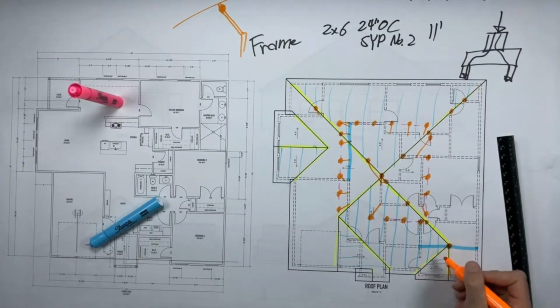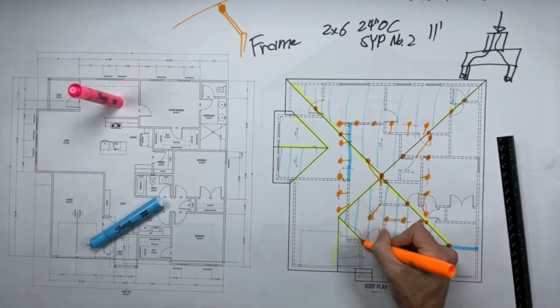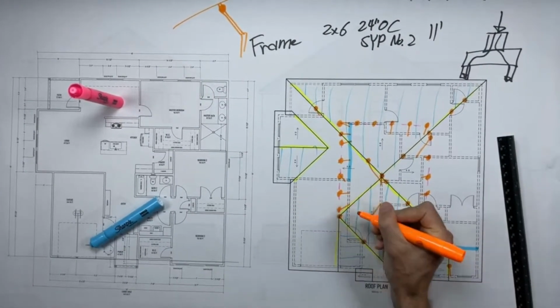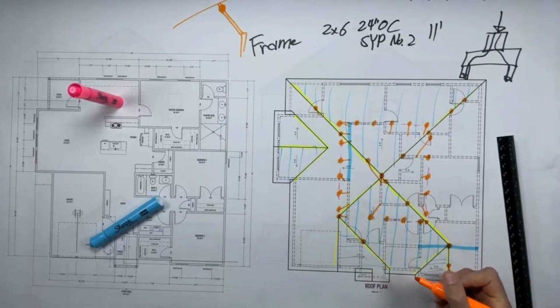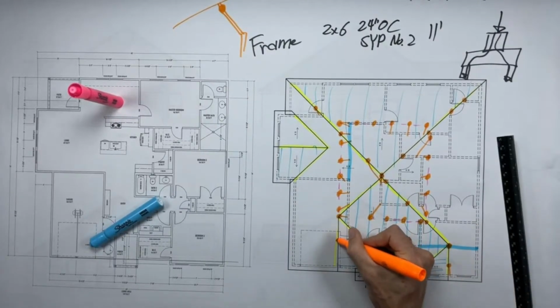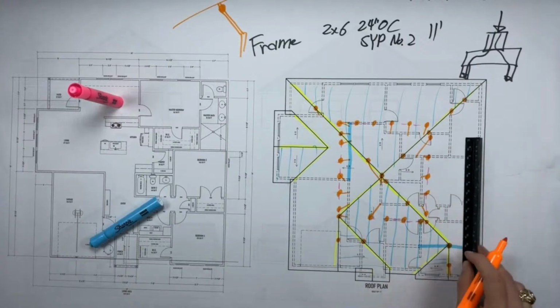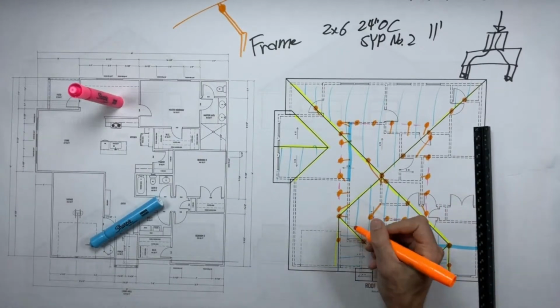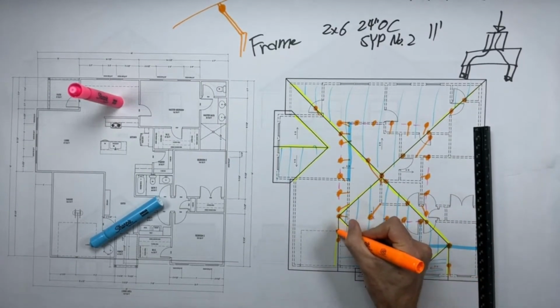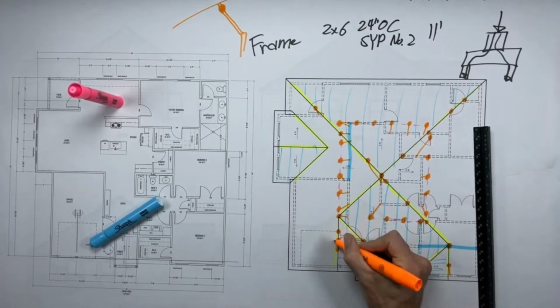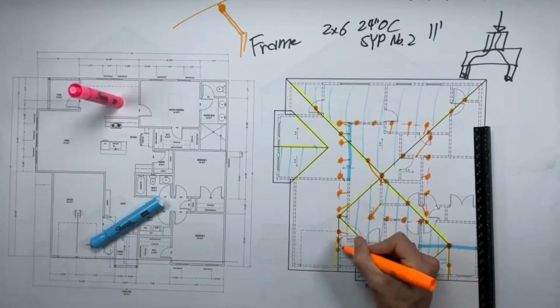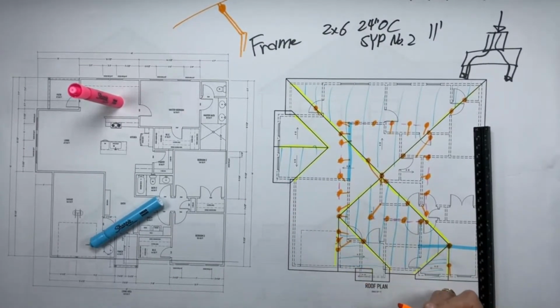Okay, and that one's fine. This one, look, I got a wall right there, super easy. This joint right here, I've got a wall right there, nice and easy. This dude, okay, wait, this is a ridge, so I gotta do every 4 feet or so. It's basically about 10 feet. So, if I'm being responsible, I'd put one in here and I'd put one in here, get rid of that. This can brace the wall and that can brace the wall because I'm decently high up in the roof. That takes care of that one decently easily.